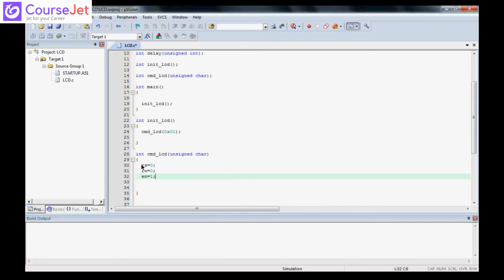So before doing all these things, I'll do one thing: I'll assign this particular value, which is unsigned char t, or unsigned char anything, data or anything. I'm just writing it like t, and assigning this to my LCD. First I'm sending my data to my LCD data pins, which is port 3, and then I'm saying that whatever I'm sending, register select is equal to 0, which means that this is a command and I am writing it into it, enable it.